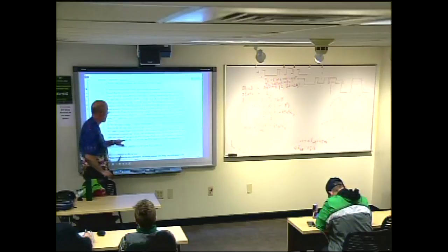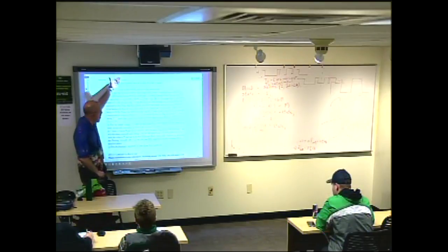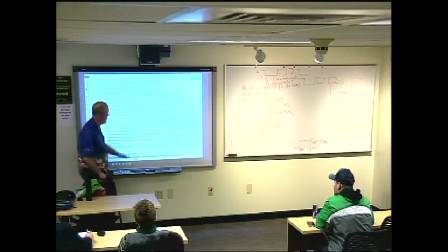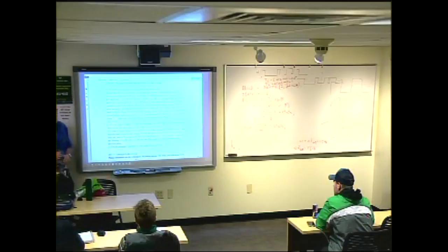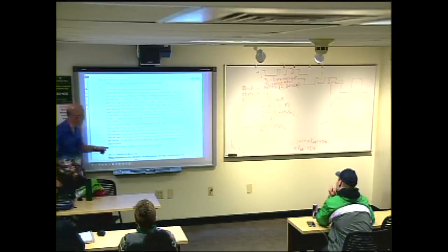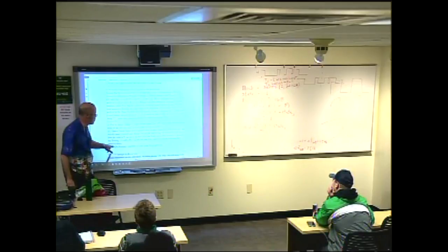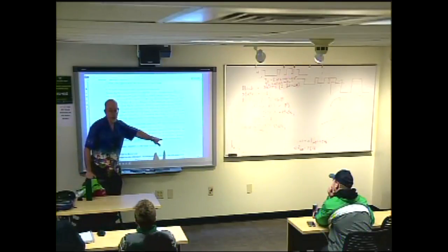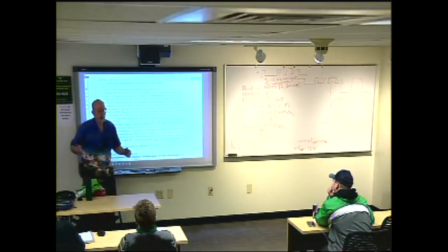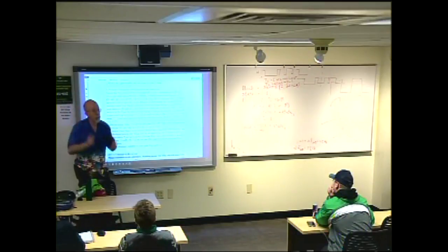Then plot your flicker noise with the same low-pass bandwidth, which should give you an idea of what happened in the previous problem. And I want you to plot what's happening to that flicker noise with a bandpass filter. Okay? And then I want you to plot the frequency spectrum just from the last one, just from the bandpass. I want to see what the frequency spectrum of just flicker noise coming through your bandpass filter looks like.